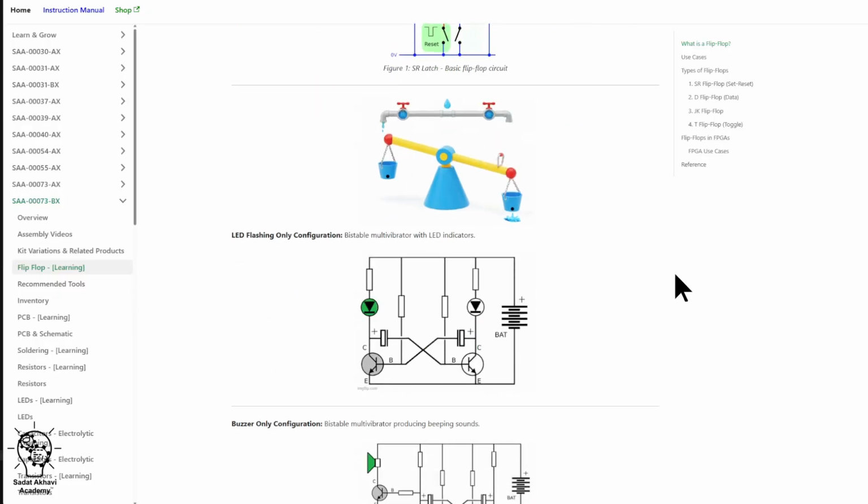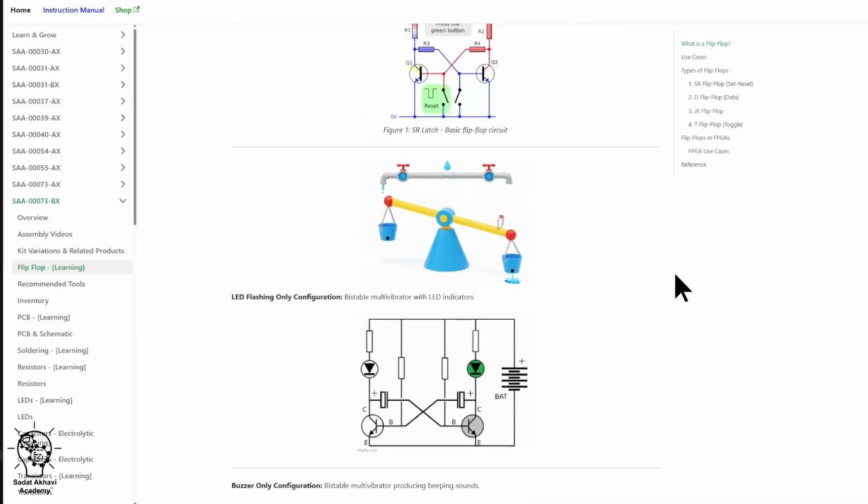Astable is another common configuration of flip-flops. In this circuit, capacitors charging and discharging control the switching behavior. The capacitors act like a leaky bucket. They charge from incoming current, then they slowly discharge over time, and the other bucket charges. This charge and discharge process controls the state of the flip-flop.